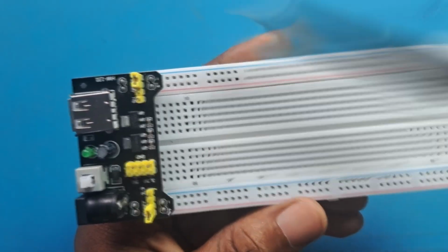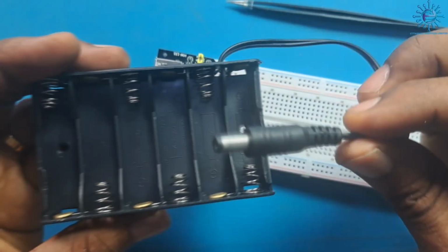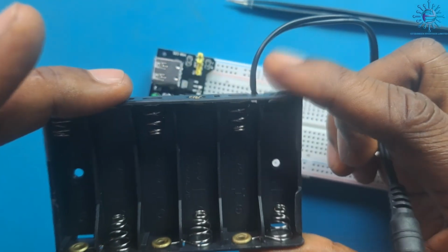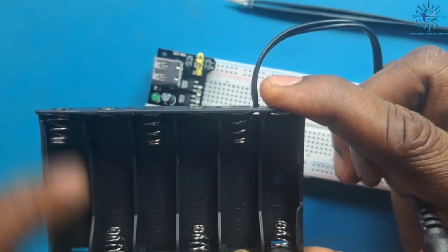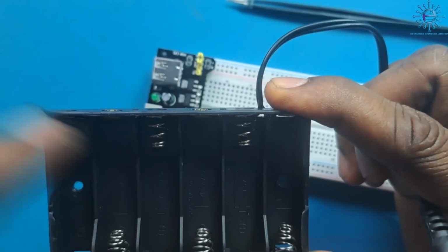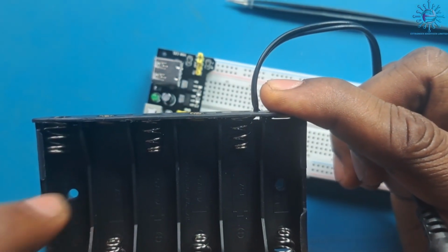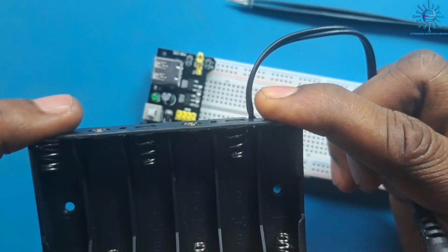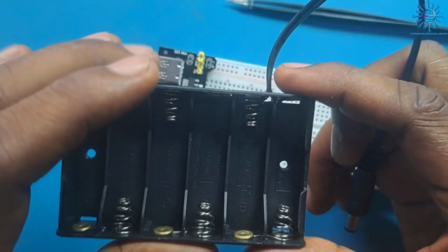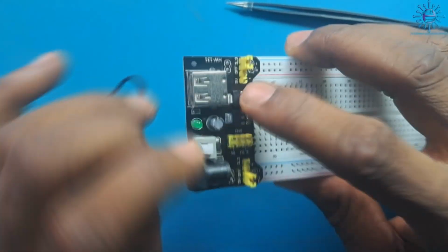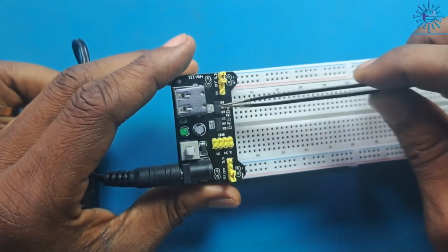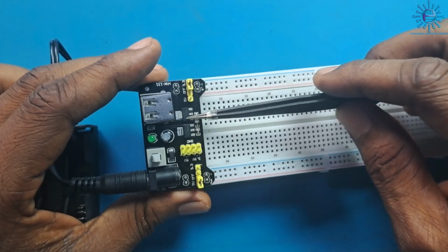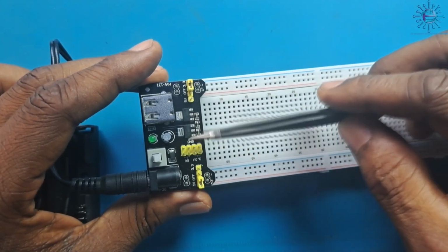And to get that input voltage, we will connect our battery to the module. This is the battery holder. So what we will do is to connect batteries here. We will connect AA 1.5 volts batteries, about 6 of them. Each one is 1.5 volts. So when we have 6 of them, we will get 7.5 volts. When we supply that 7.5 volts to this power supply module through this power jack, the regulators here will help us regulate that 7.5 volts to either 3.3 volts or 5 volts.